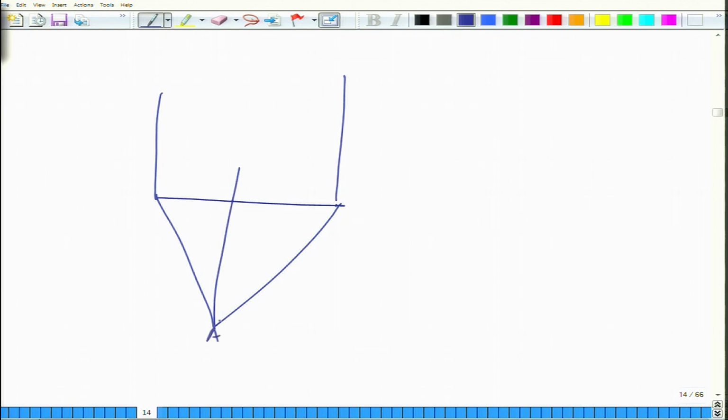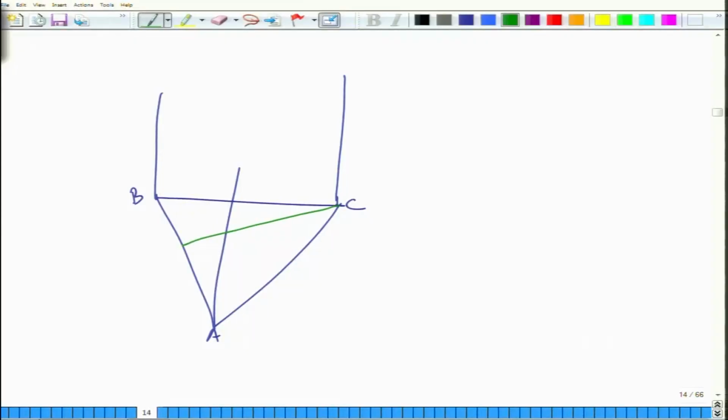Essentially these A B, B C and A C are nothing but isopleths, but they are vertical binary phase diagrams. Here you want to go, for example, you want to draw this vertical section. Okay, so this is an isopleth. You may want to draw another one, which is, let us say, like this. So these are the isopleths which give you evolution of phases as a function of temperature for a given ratio.